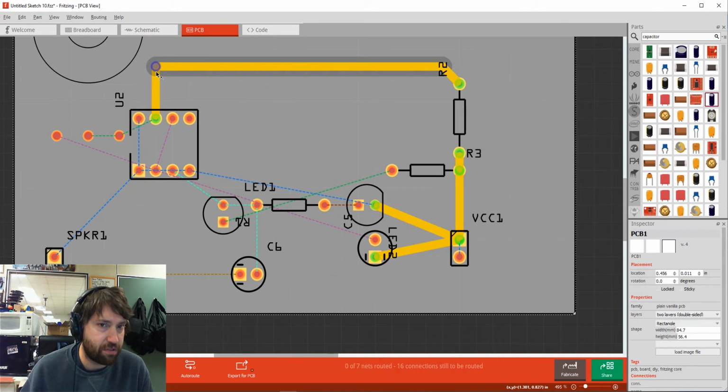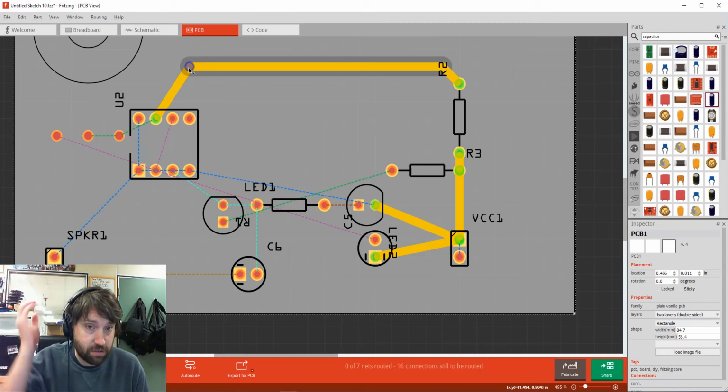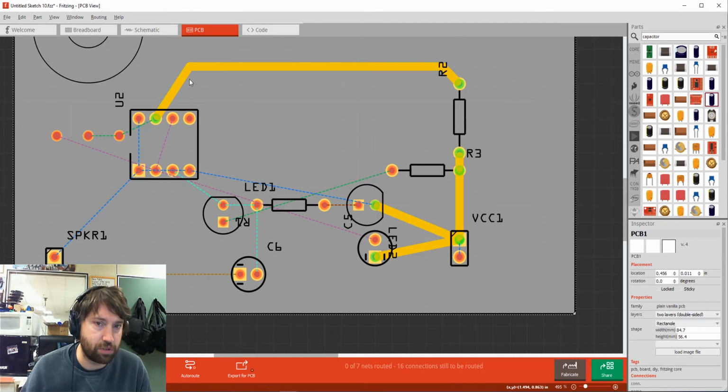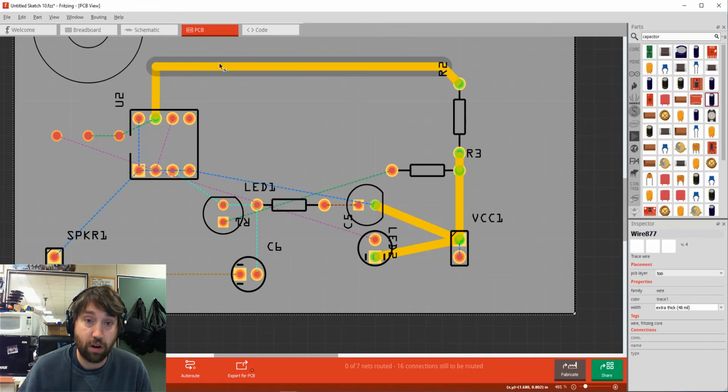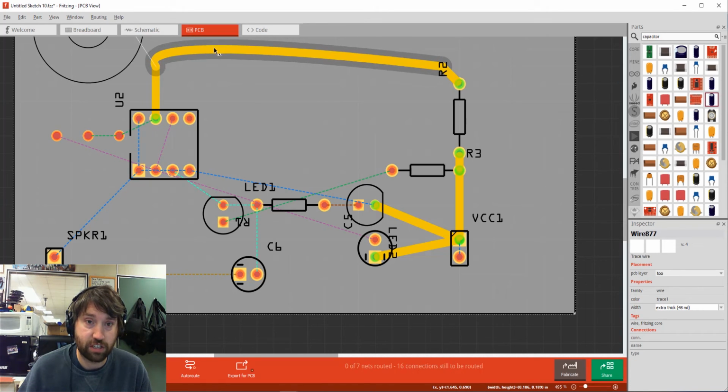Because of the type that we're manufacturing, I think we can get away with some angles, but really 90 degrees are the worst. So if you can have them be bent at a different angle than that, a less sharp or more obtuse angle, that's going to give us a higher success rate. Certainly if you look at professional PCB design, you'll see a lot more curves in the traces.